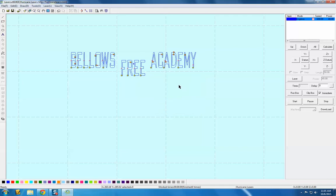Say OK. Now, if I'd like to see what this is actually going to do, like a simulation, I can go up to Laser, and I can come down to Simulate. And since I'm engraving, you can see that it fills in all the words. At that point, if that's what you wanted to do, you wanted to engrave this, it filled in the words, you're ready to download your file.